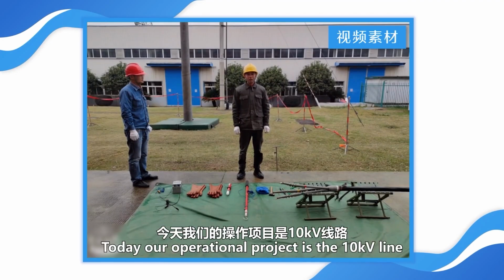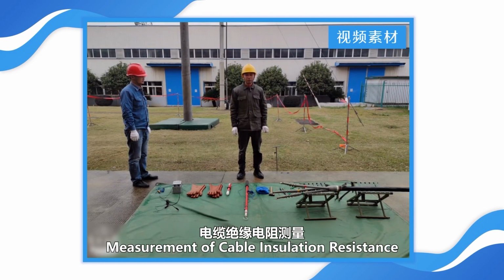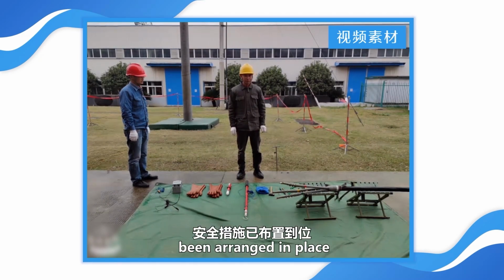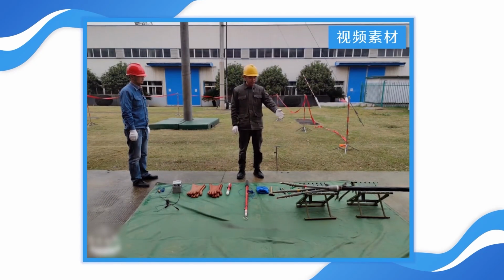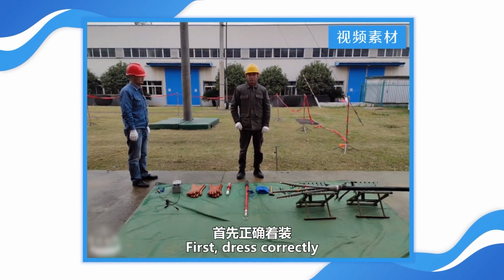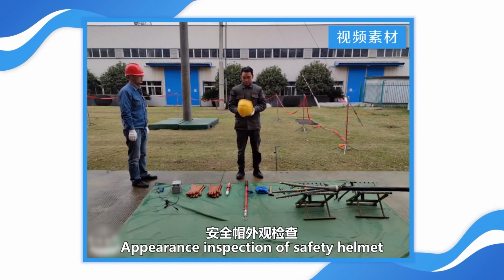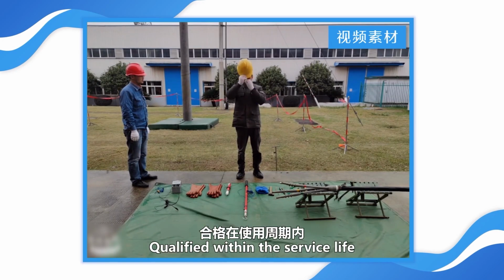Hello everyone. Today our operational project is the measurement of 10 kilovolt line cable insulation resistance. The work permit has been processed and safety measures have been arranged in place. The cable is ready. First, dress correctly. Appearance inspection of the safety helmet: qualified within the service life.